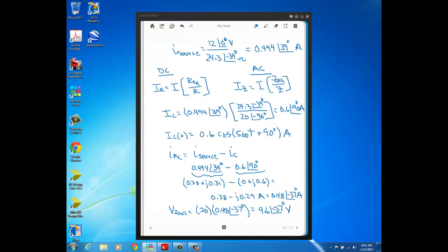Okay, so we're going to do a couple more problems in the next couple of videos, again using AC circuit analysis, and hopefully if you don't already see it, you'll see eventually that solving these AC circuit problems is the same concept and thought process as solving a DC circuit. The only difference is we're dealing with vector quantities now, phasors, which are vector quantities that represent sinusoidal voltages and sinusoidal currents, and then impedance, that's generally a vector because it has a real and imaginary part in general.